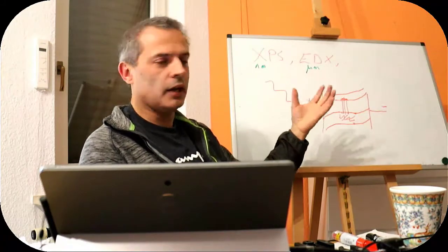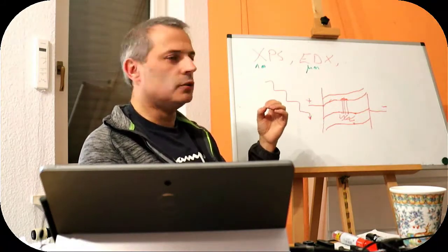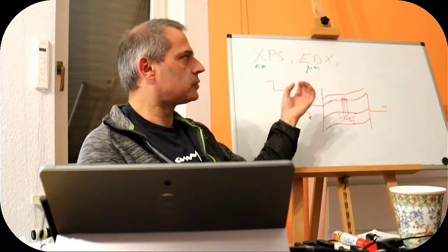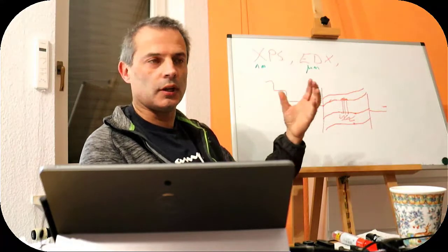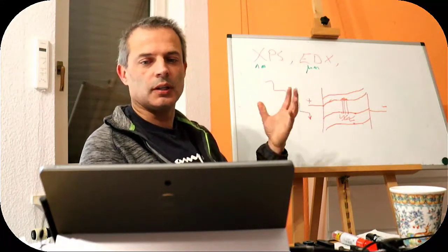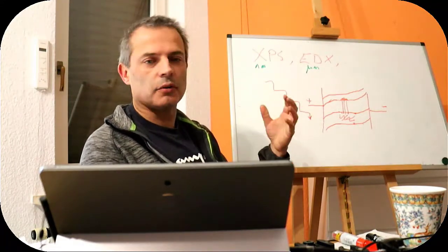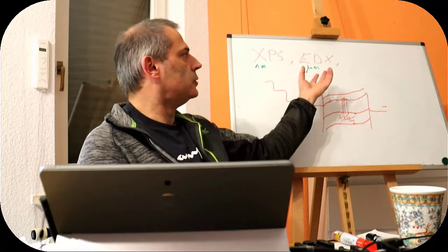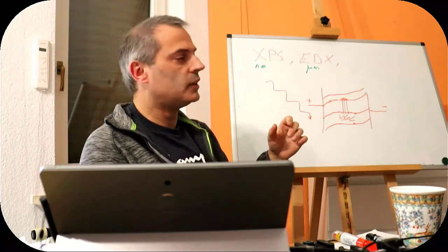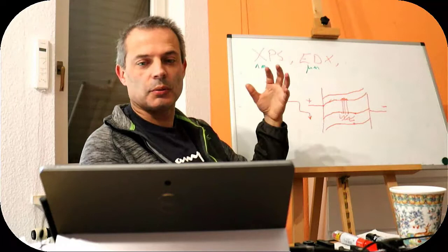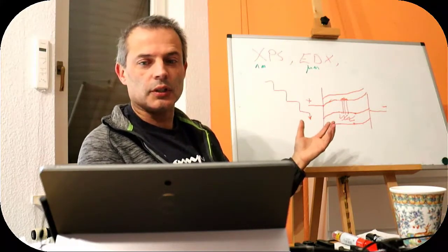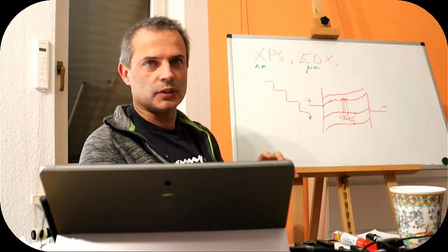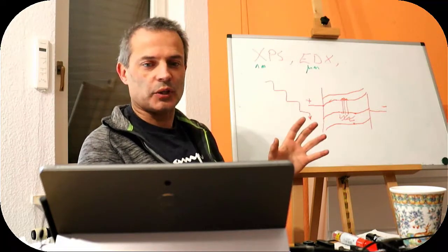Typically in a practical system you don't measure the X-ray spectrum at the same power that you measure your images. It depends on a lot of things. You often have to turn it up slightly. You sometimes have to turn it down to avoid two photons coming at the same time and overloading the ability of the computer to do the next step, which is to fix the spectrum.